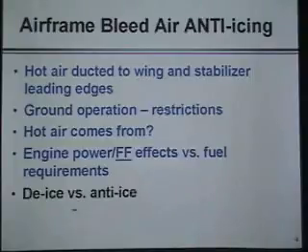If you didn't know, ice tends to stick first to the smallest radius items. For instance, antennas have a small radius. The ice will stick there first. The leading edge of the vertical and horizontal stabilizer have a smaller radius curve on the leading edge than the main wing. So if you look out on the main wing and you see icing, guess what the icing's like on the tail? Worse. Think about that for a minute. If you see icing on the wing, it's worse on the tail.